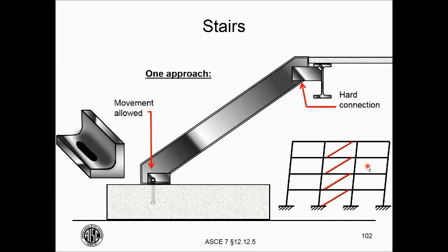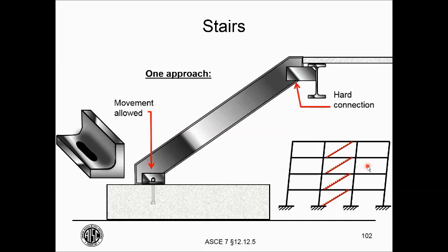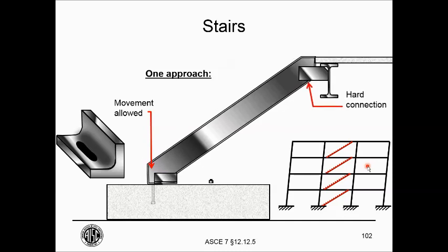So as the earthquake happens and there's a story drift demand at this story, we move back and forth within that slot in the connection, with the understanding that it is not inconceivable that the forces get larger and the drifts get larger under the MC, and even if you damage that connection, you are not losing the gravity support. And I think that's the optimal condition for the stair, to be able to deform even beyond the predicted limits and still maintain the integrity of the stair.